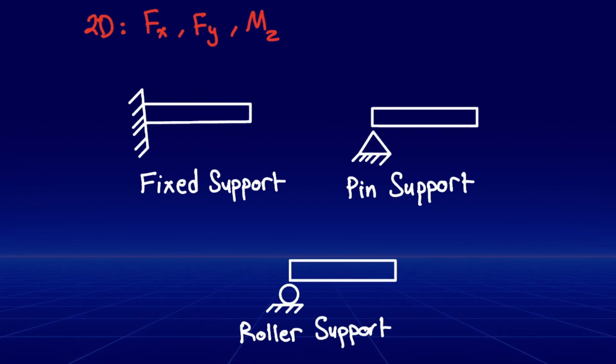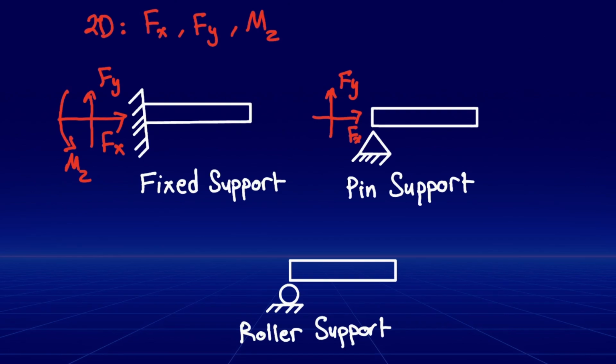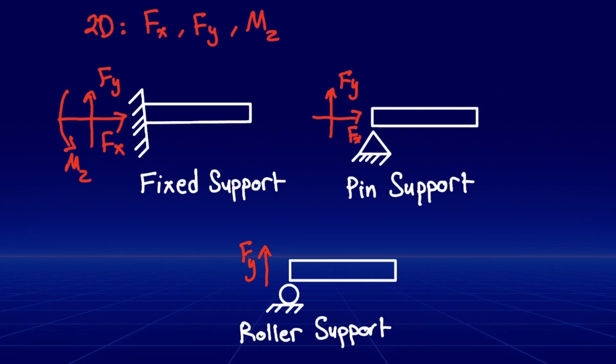For instance, a fixed end resists both translation and rotation, leading to reaction forces in both directions and a moment. On the other hand, pin ends resist translation but allow rotation, resulting in reaction forces but no moment. Additionally, roller supports resist translation perpendicular to the surface but allow movement along the surface and rotation, leading to a single reaction force.